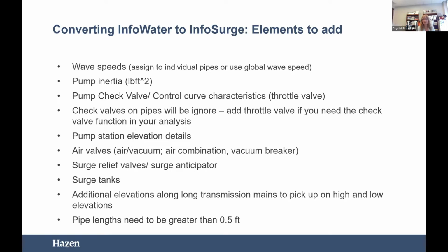Surge relief valves and surge anticipator valves, there are several ways to model them within the modeling software. One is based off timing and the other is based off of pressure. Surge tanks, you can do closed surge tanks, which would be your compressor style surge tanks. You can do one-way surge tanks. You can do bladder surge tanks. And I think I'm missing one, there's another one, but I don't use it very often. But those are available.